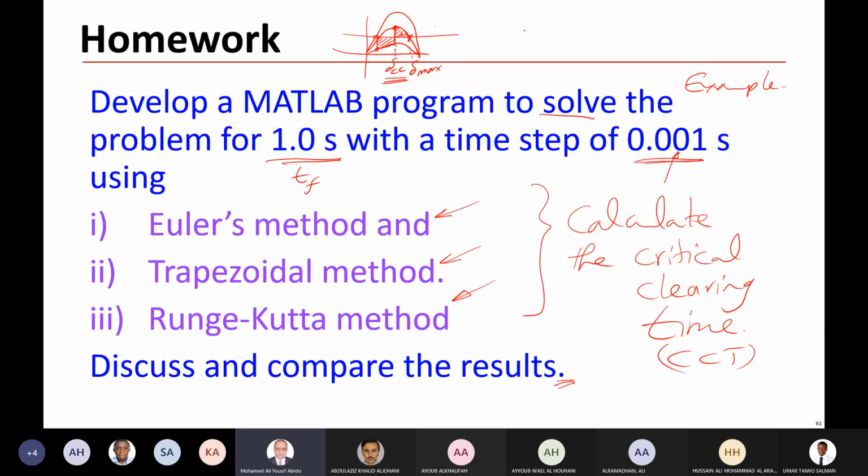If the power during the fault equals 0, we can write d squared delta by dt squared equal to omega s over 2H multiplied by Pm minus 0. And this is constant now, so we can double integrate in order to get the time.